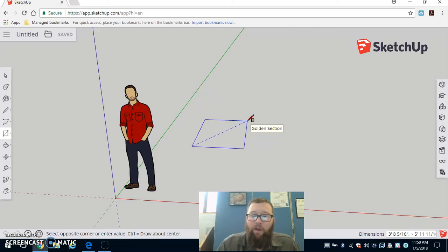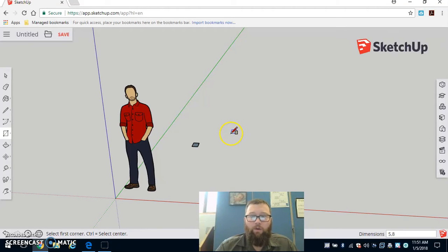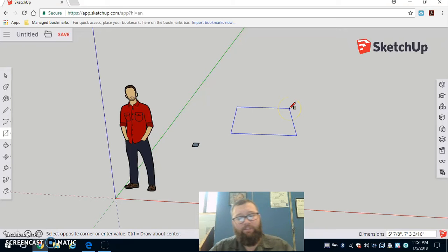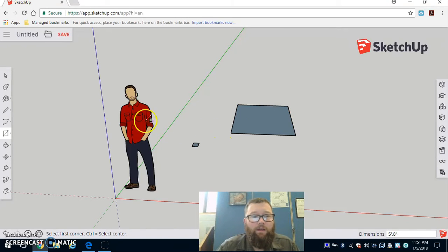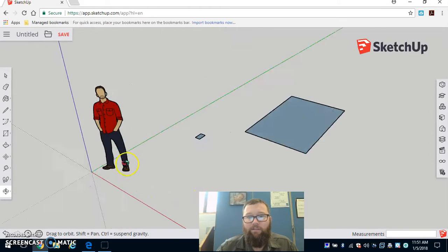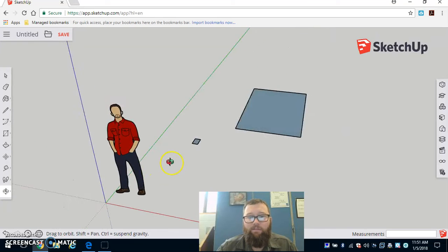If I start typing a number, that will clear out and be replaced by the number I type. So if I type 5, 8 and hit enter, it set it to 5 inches by 8 inches. Now if I want to create one that's 5 feet by 8 feet, I would have to type 5 apostrophe, 8 apostrophe. So now it's notated as feet. And if I hit enter, it created a 5 by 8 rectangle on the ground. So if we look at those, we've got 5 feet by 8 inches, 5 feet by 8 feet, and 5 inches by 8 inches.